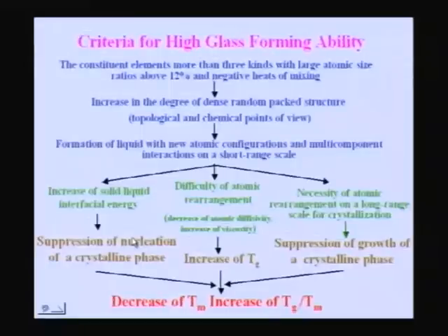When a liquid is giving you a crystal, what gives you the activation barrier for a crystal to form? It is only the interfacial energy. If the interfacial energy is very low, then the crystal formation is very easy. If we can somehow increase the interfacial energy or the surface energy, then the crystal formation is more difficult. That is why we always say that liquid to crystal formation is more difficult than crystal to liquid formation.